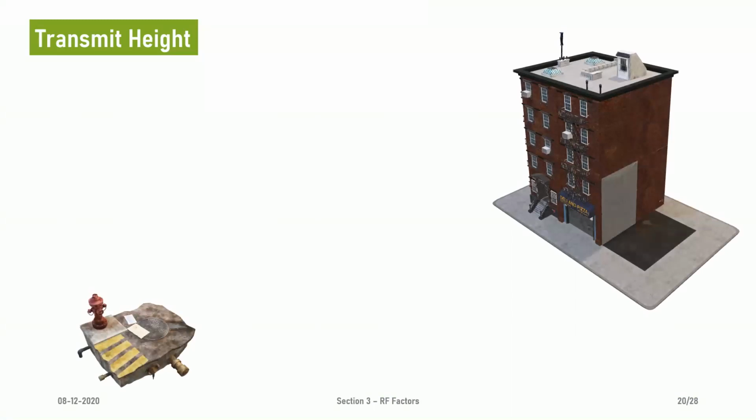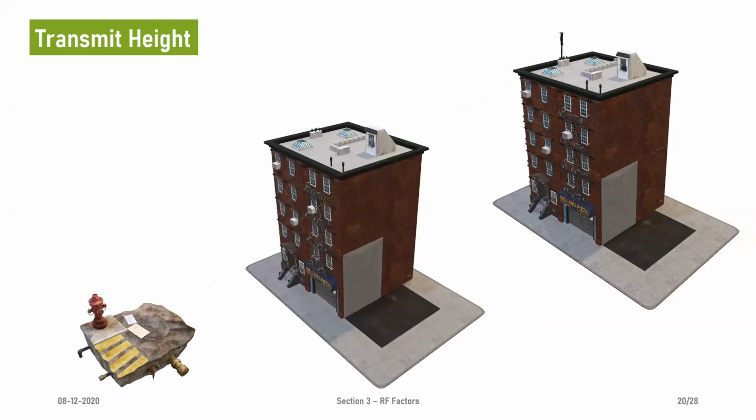Let's assume we have a manhole monitoring sensor and a gateway residing on top of a 3-4 story building, or on a pole that is not very tall, say 2 meters of height. After incurring the enclosure attenuation, the manhole monitoring sensor would ideally see the gateway directly. I hope that always happens, but it's not the case, because you're making solutions where a line of sight path is essentially not possible, as you see a variety of obstacles in between. So whenever your signals transmit, they first have to diffract from the obstacle and then reach the gateway. Of course, that gives you a diffraction loss compared to when there is a line of sight path condition.